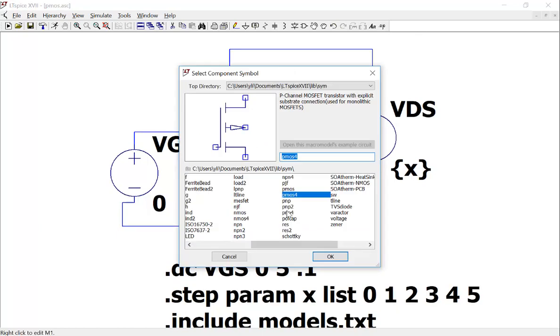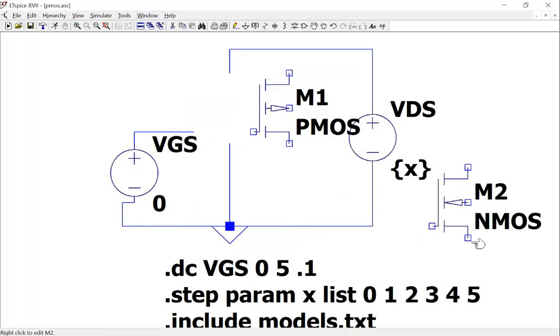So, for example, if you grab an NMOS here and you want to tell which one's source and which one's drain, it actually doesn't matter because the CMOS is symmetric. But it's better to have a good practice over here. So the gate is closer to the source, so this is the source. This is the drain, right? If you rotate it and put a high voltage here, using it as a drain, it's still going to work the same way. But it's just not a good practice.